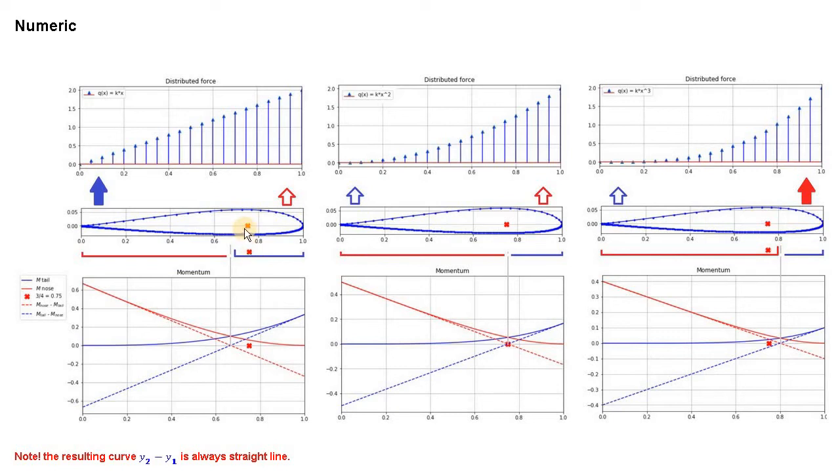Okay, and the stability has nothing to do with this point. So in the worst case, if you are going to choose it in the wrong place, you're going to compensate it with other aerodynamic surfaces, so you're going to lose efficiency, but it's not related to the stability of the plane. Okay, well, actually it's going to be a bit unstable if you're not going to place it exactly at the point where you have the zero momentum, but it's not the problem.